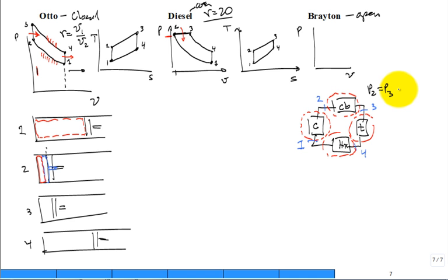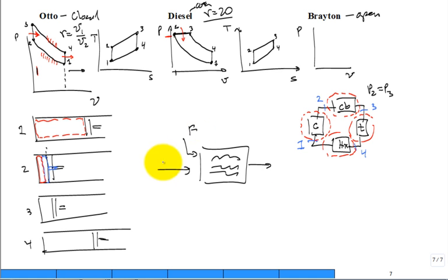Well, what's happening in the combustor? It basically has air coming through, and it's a little complicated, but you throw in the fuel, and you have a spark plug going click, click, click, or once the fireball is going, it doesn't need the spark plug, and it's just burning, continuously burning. Then it goes out. All right? So fuel with the air, and somehow it got burning, and it's staying burning, okay? Is there a mechanism to increase the pressure from the inlet state 2 to the outlet state 3 of a combustor?